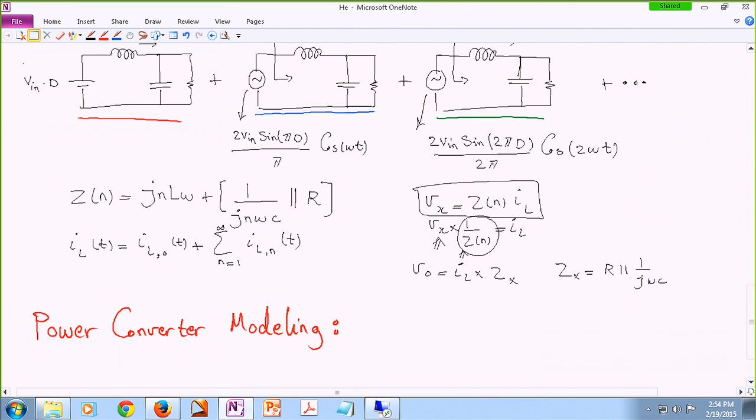Or depending on what is happening in the car, for instance, if you're starting the car, there might be a huge current being drawn, and then even 12 may drop to maybe 6 volts temporarily. So your input voltage is variable. Your load would like to see again a constant voltage of 3.7 volts. So sometimes your input source is variable, sometimes your load is variable, and you should be able to regulate the output voltage regardless of the changes. So that's why we are trying to look at a converter from a control perspective.